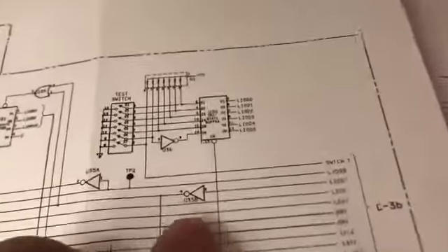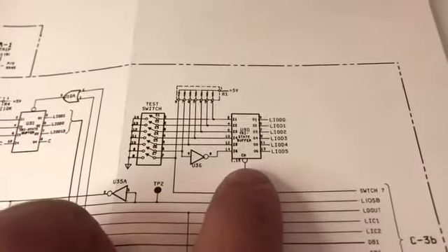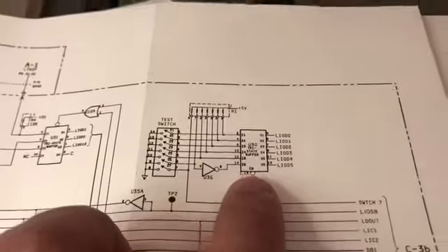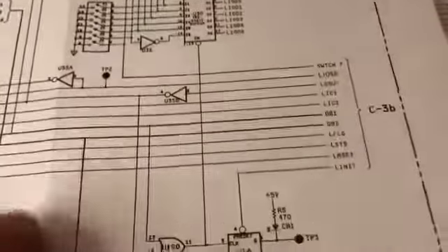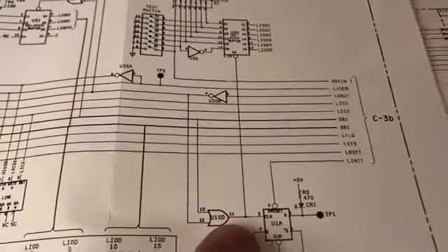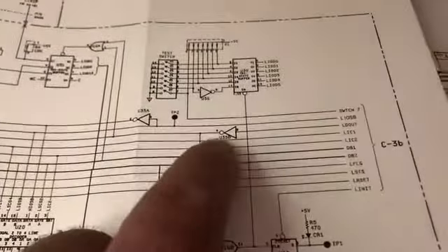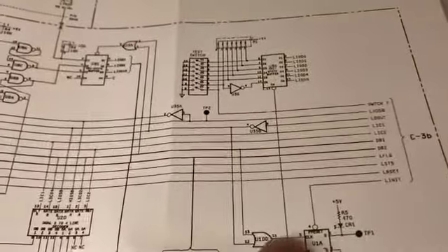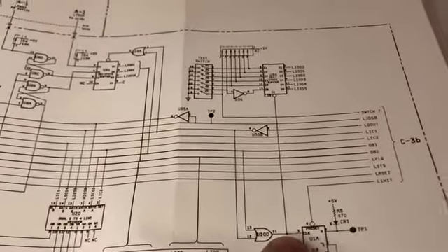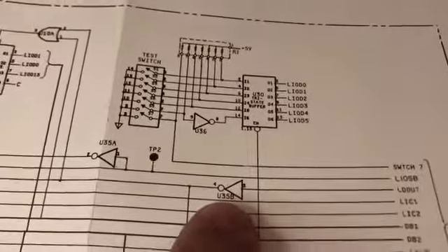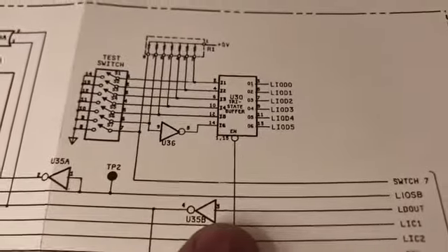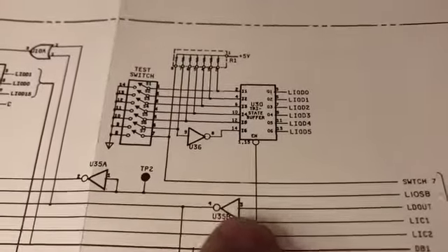And what I found is that this enabling gate, actually there are two pins, pin number 1 and 15, are driven by this gate, which in turn is driven by this. Since I had several times a weird signal over there, I'm going to check this. So pin 3 is the input, pin 4 is the output, of course it's an inverter. So this is what I have found.